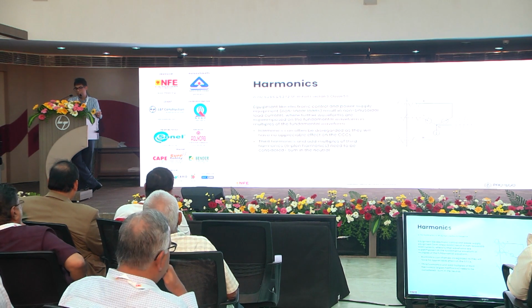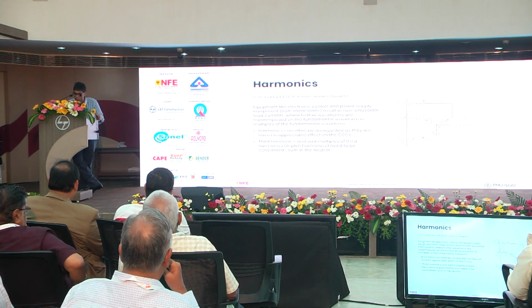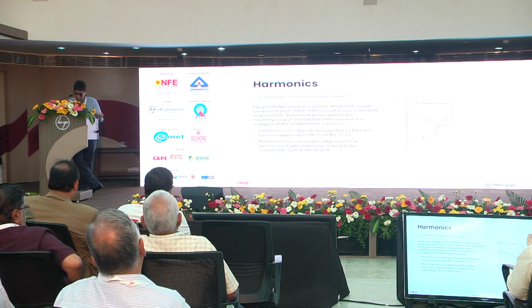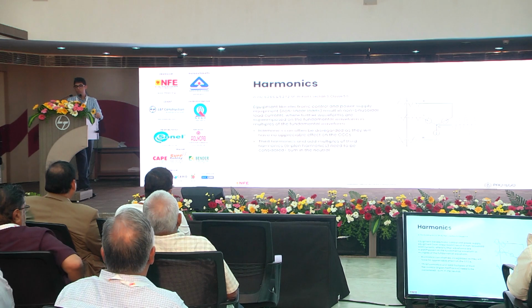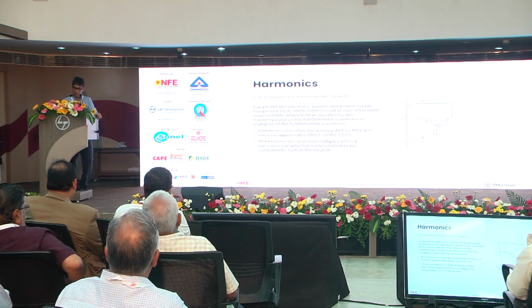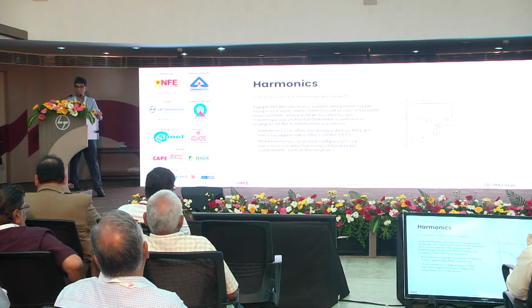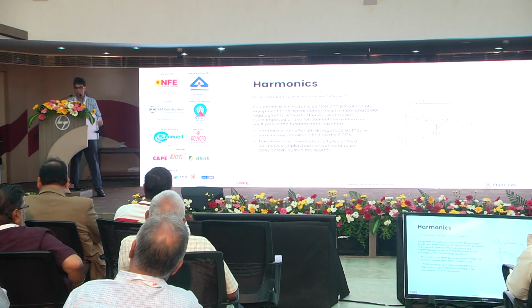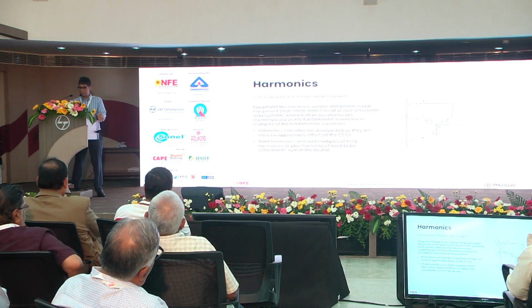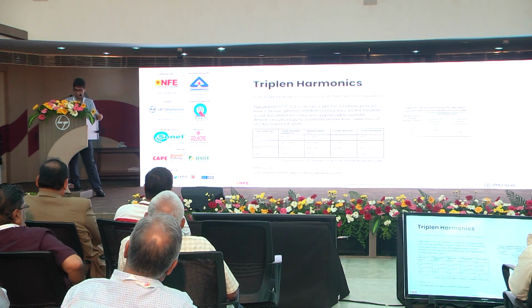You can see this is going through the full cycle. I think in this case, a little more. It's definitely more than 2 times the fundamental frequency. So now, if I have this in the red phase, this in the yellow phase, this in the blue phase, see what happens? The 3 phases cancel out. But what is happening in the neutral? It's conducting. And when you take the root mean square of this, you're getting a current. This has to be considered. Now, how do you consider this?